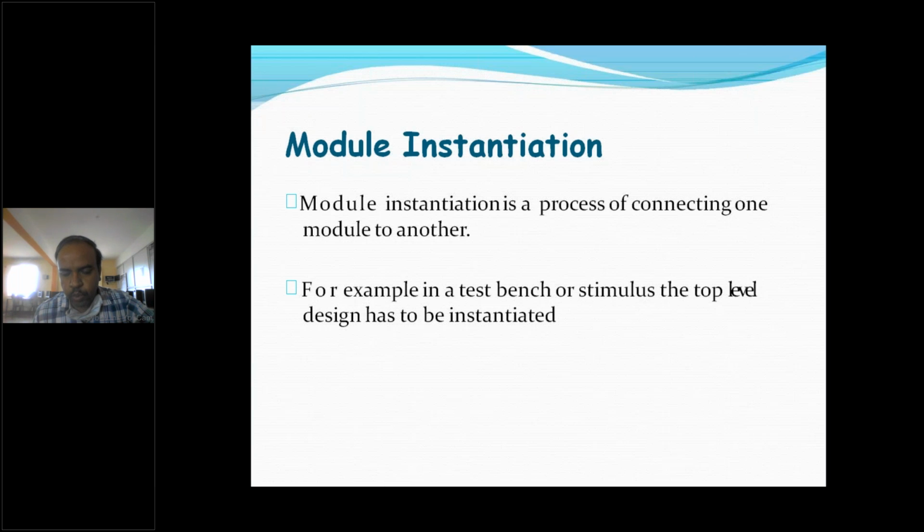So we are checking the AND gate, right? For the AND gate, y equal to a dot b, so inputs are a and b. If you write the truth table for the AND gate, I can write a b, then y equal to a dot b. You can assume a b as 00, 01, 10, 11. Then output y equal to a dot b means output will be high if and only if both the inputs are high. So I'm getting output as high only for the last iteration, right? For that we are using the test bench, which we'll see later. We take Xilinx again, then I'll show you how to run the code with respect to the simulator.